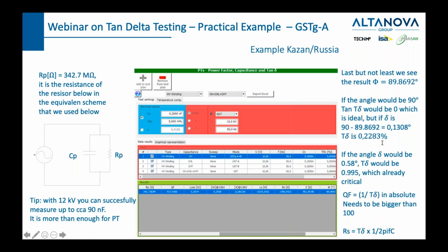The oil test can also tell you what might be the reason why the insulating properties are not good. If you have too much hydrogen, then it could be partial discharge. If it's too much acetylene or ethylene or something like that, it can be a hotspot, and it gives you the reason. But tan delta tells you if it's insulating or if it's not insulating. So in that case, it's more precise because it doesn't check just the oil, it also checks the state of the pressboard, the cellulose, the paper, etc. And you need to know that. Otherwise, you might think that the oil is perfect and basically you have a lot of water in your cellulose.